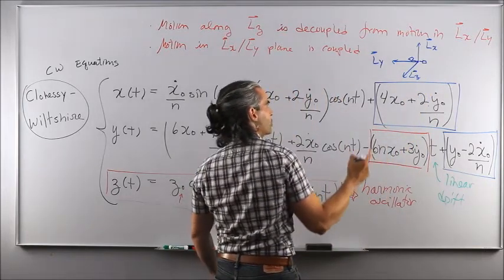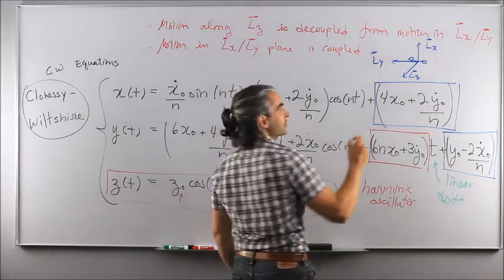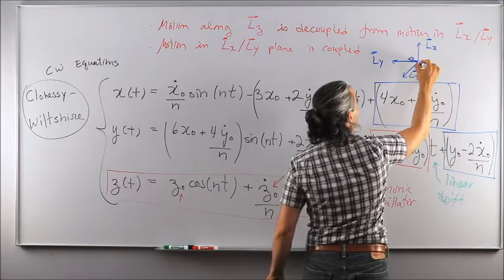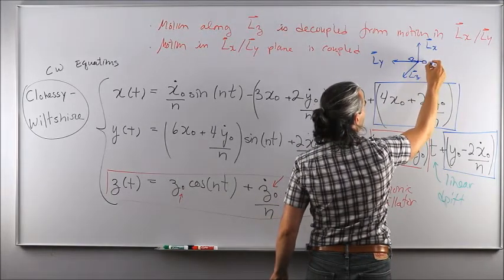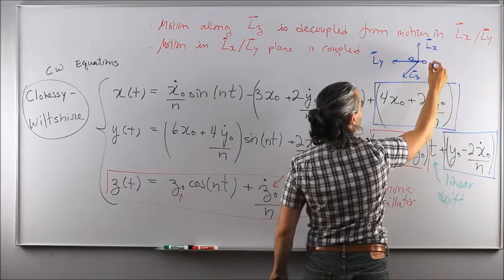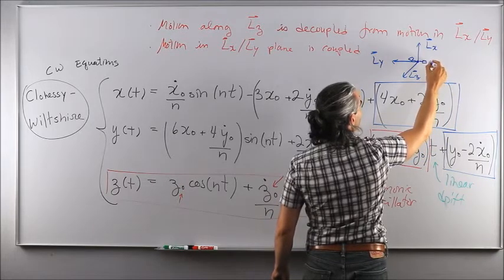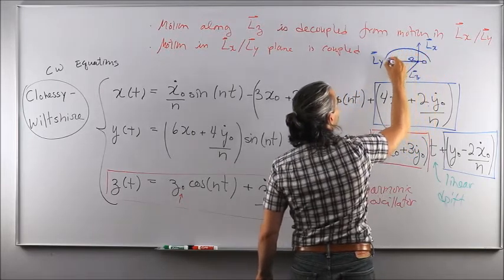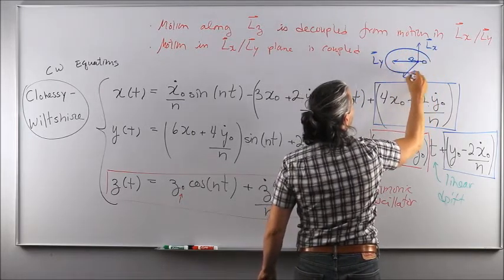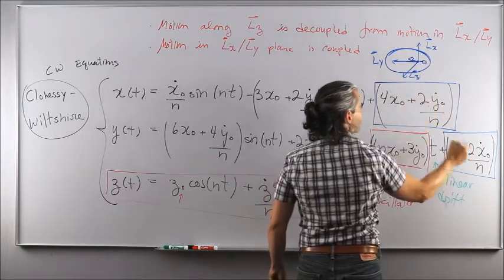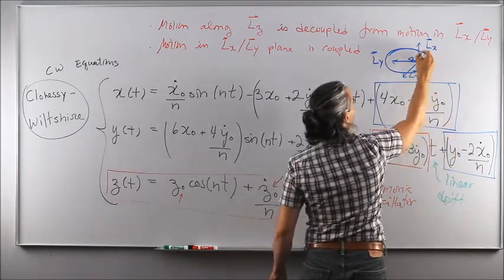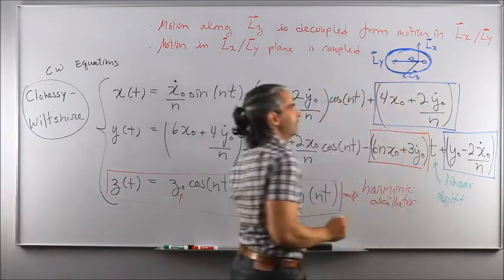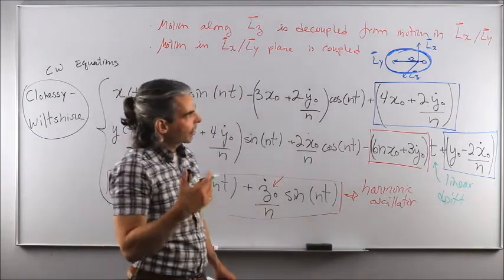Well, you would see the motion of the chaser spacecraft with respect to the target spacecraft to be something that isn't centered about the target spacecraft. For example, we're going to look at different formations in a couple of minutes, one of which is an in-plane elliptical motion, so an ellipse in the Lx, Ly unit vector. If you don't cancel those two offset terms, we would see the relative ellipse in terms of relative motion in LVLH to not be centered at the target object. And that could be kind of annoying.